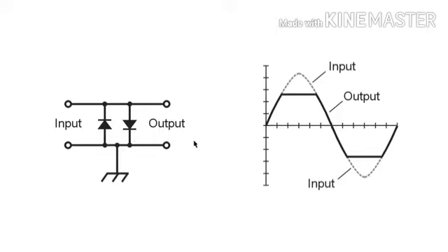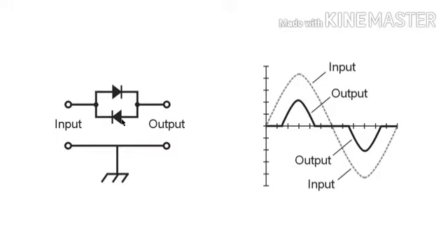Now you can also apply this same principle, reverse parallel semiconductor diodes, to get a completely different phenomenon. However, you can also take that reverse parallel diode combination and connect it in series with the circuit. What you get in a case like this is something called a threshold detector.